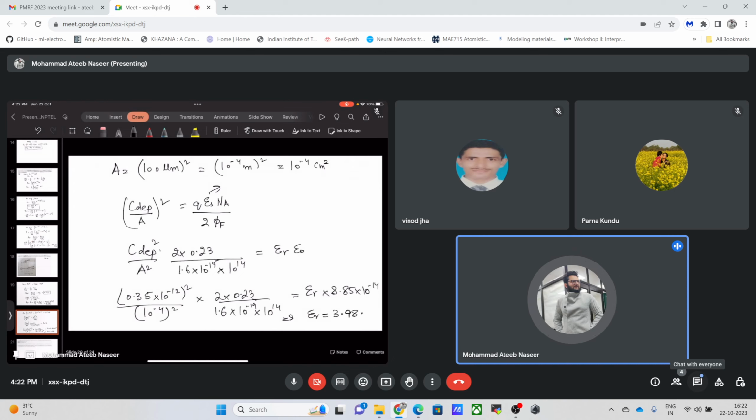So the solution for this, since this is an exponential decay, it corresponds to a resistor being required, and in the deep triode region we have this MOSFET behaving as a resistor,